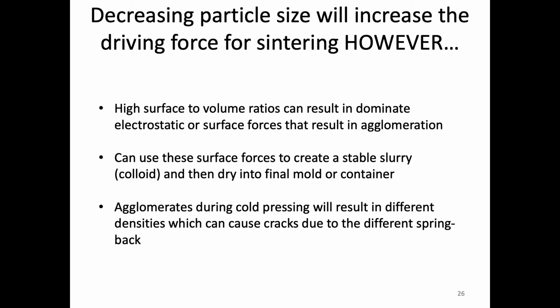Okay, so I also wanted to mention the effect of particle size. Chances are, if you go out into the literature on ceramics and ceramic sintering, one of the big things that you're going to see is a push for smaller and smaller ceramic particle sizes to be used. And that is a result of the driving force. So the driving force for sintering is that removal of excess surface energy, right?